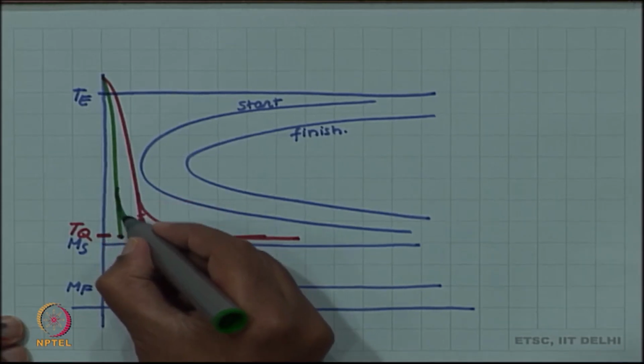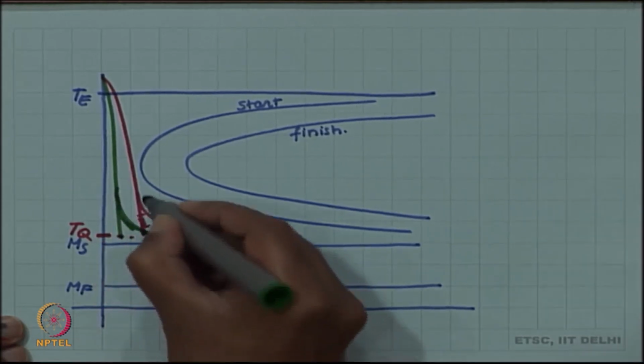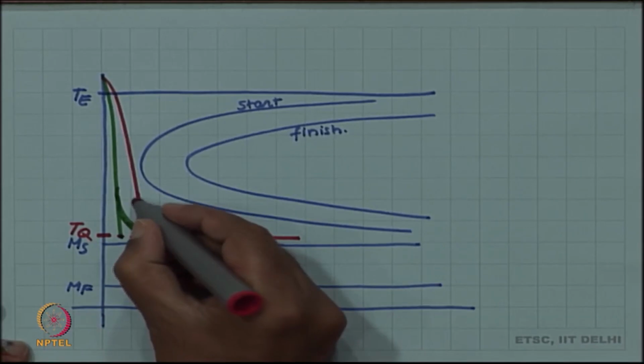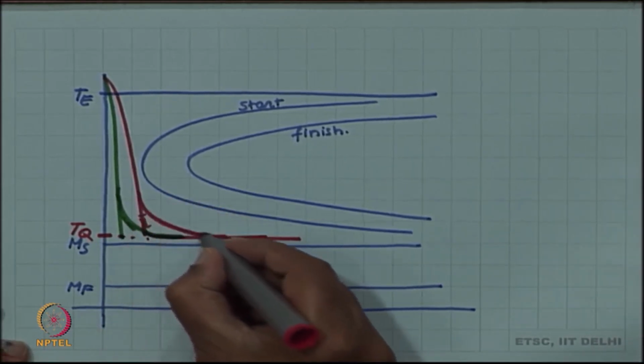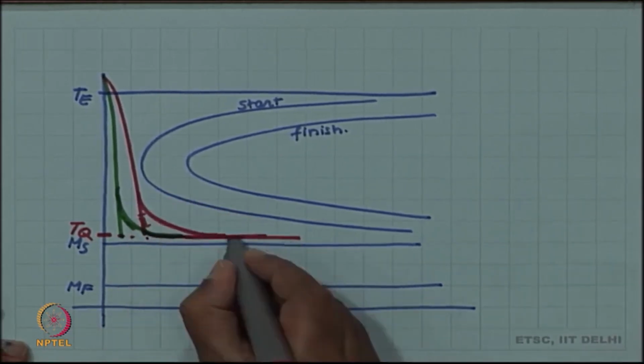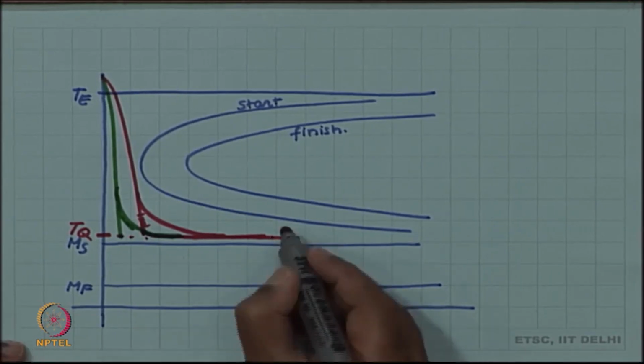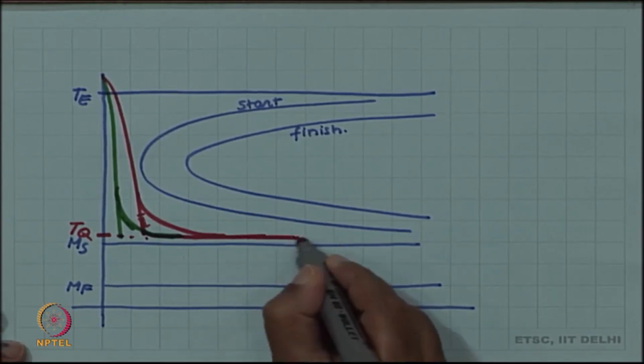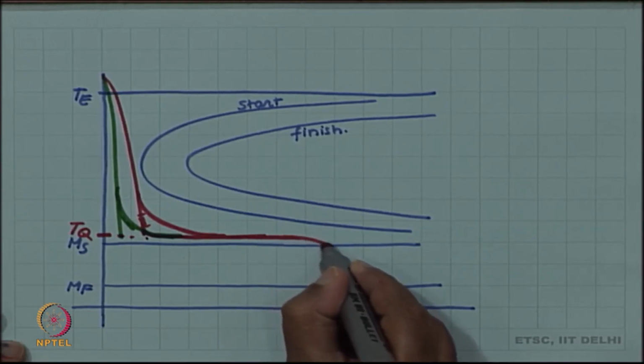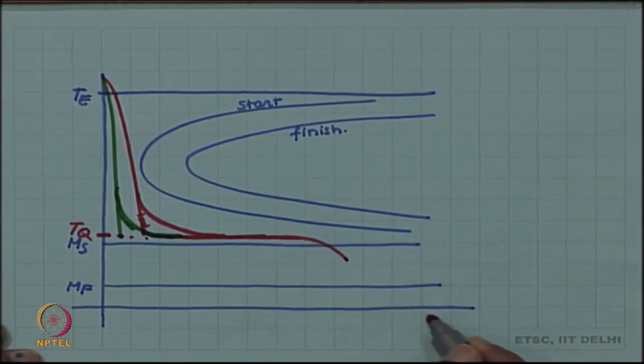there will be time enough for the inside and the outside to come to the same temperature, and then once they are at the same temperature, they can again be cooled and can be cooled much more slowly. There is no requirement for quenching now.